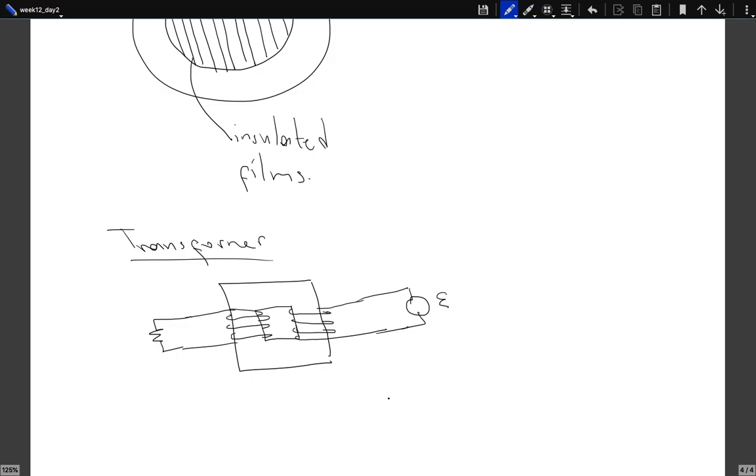Now, if you put that iron in a magnetic field, those very small magnets making up the iron get aligned to some extent. So first there is the magnetic field that you apply. Second, there is the magnetic field created due to the alignment of these very small magnets in the iron core. So without the iron you get a small magnetic field. With the iron you will get a huge magnetic field. The factor can be as large as 10 to the power 4. Not a very small effect, it's a significant effect.